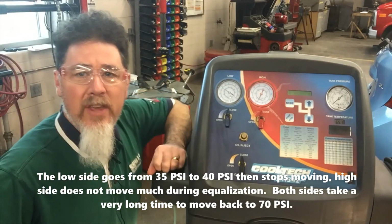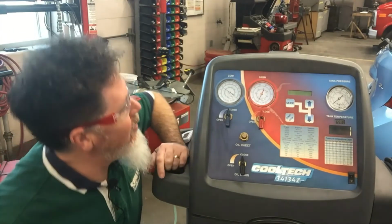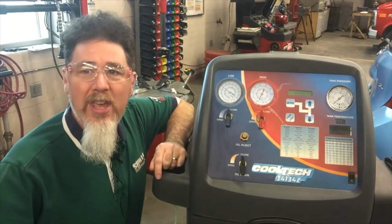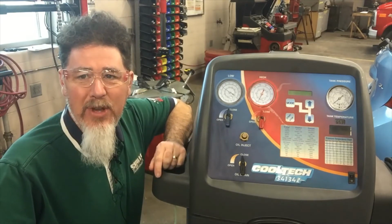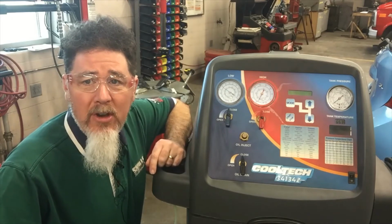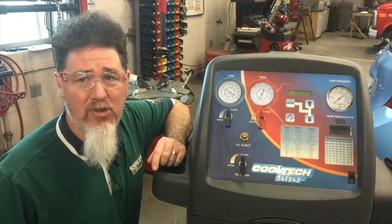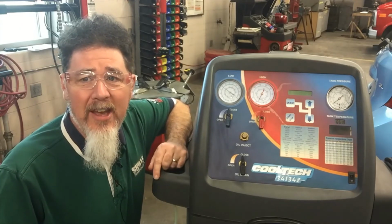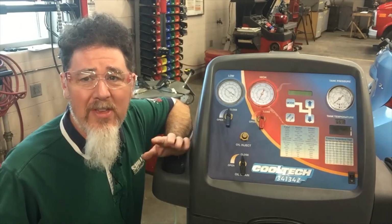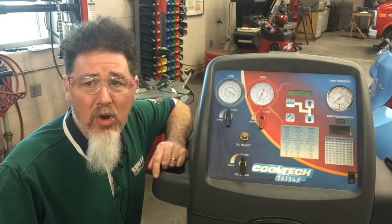If you take a look at the gauge readings, the system equalized pretty quick. They're both reading around 40 psi, which is low for a warmed up vehicle, and the restriction is before the high side service port. Again, these tests are inconclusive. They're reading the same, so it's a little bit harder to understand what's going on.